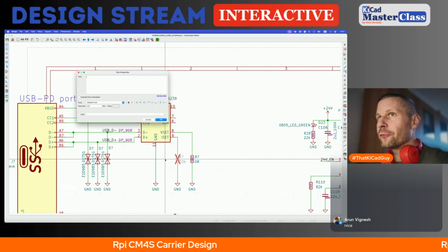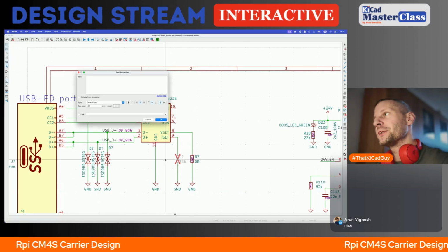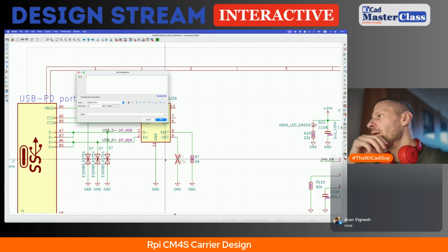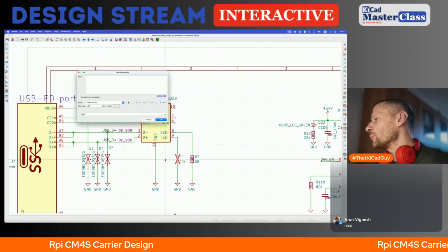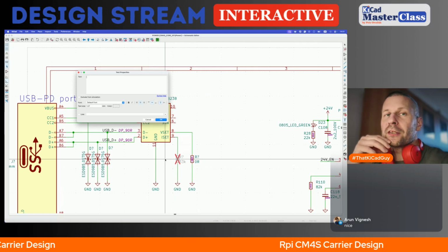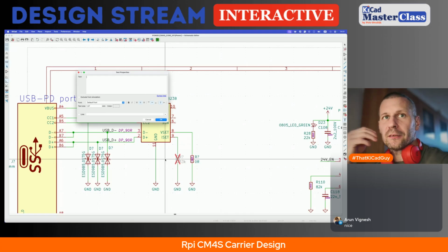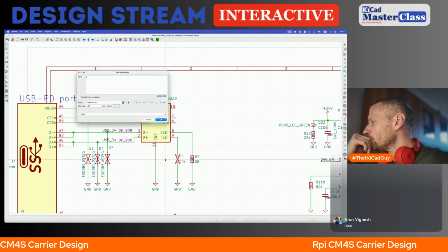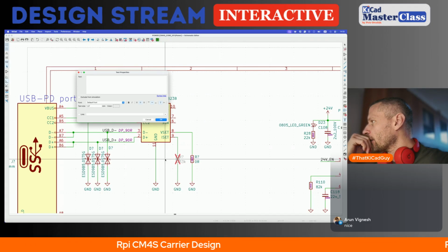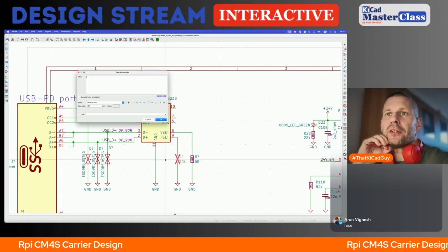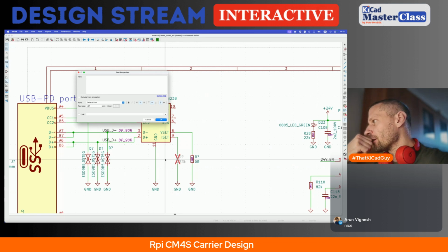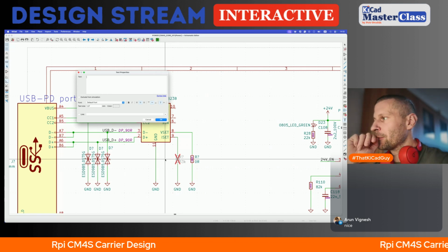the 5 volt voltage of the USB power delivery port will be used for the 5 volt domain. Naturally, with the higher output voltage, there will be a buck converter from, let's say, voltage higher than 5 volts to 5 volt, and for the simplicity, there can be a short circuit 0 ohm resistor if the buck is not populated.